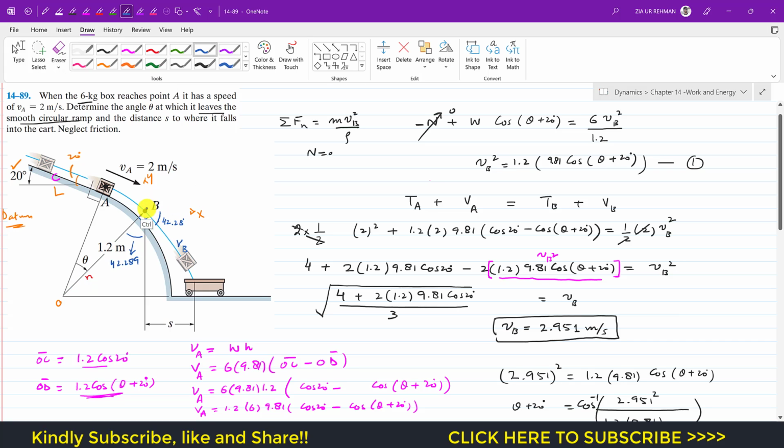Now we can resolve this VB into its components. The velocity component in the x direction is this. This will be VBx, the component of the velocity in the x, and this will be VB cos of that 42.28, and VB is known, this is 2.951. So we can say that this is 2.951 cos of 42.289. And similarly its vertical component will be acting in this direction. This will be VBy, and this one will be the sine component.